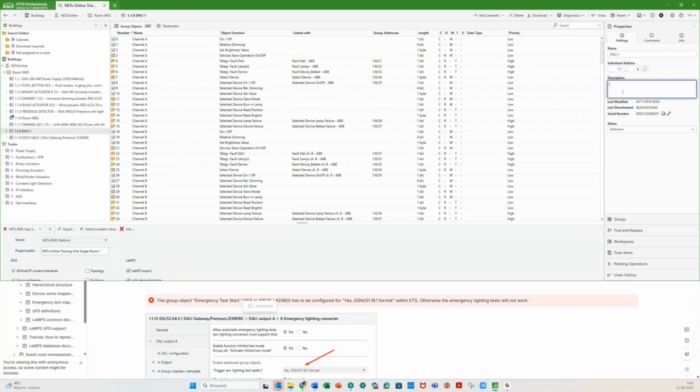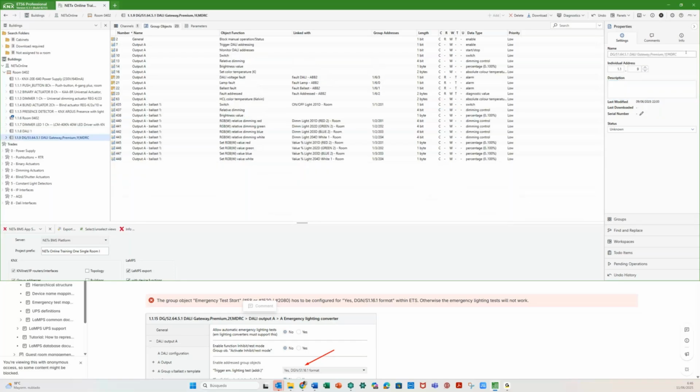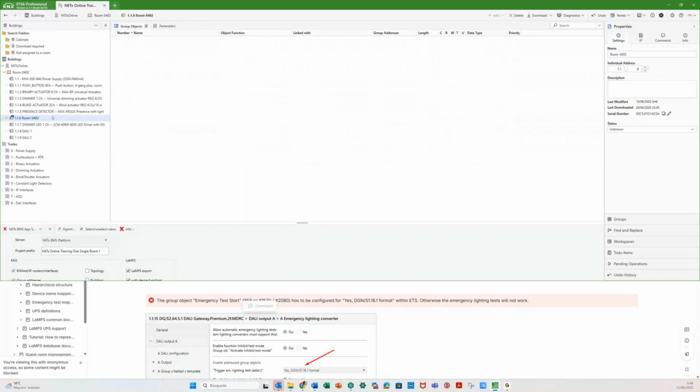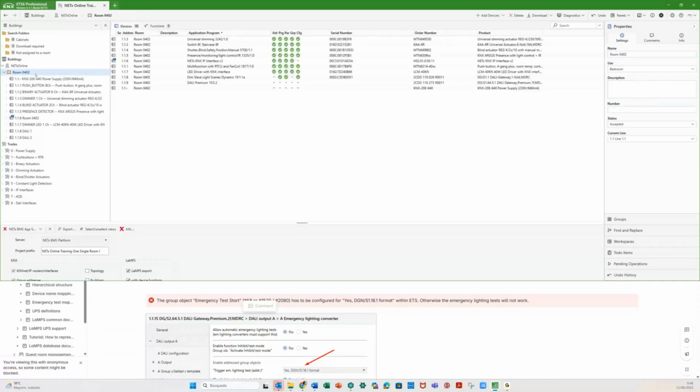And the second thing to comment on was, okay, if you remember, when I exported my projects for different rooms yesterday for KNX, I was just taking into account the room, the name of the IP gateway, the IP address, for example. But you may remember that I also changed the name of the room. It was important, I told you yesterday, because of this lamps module, because it's also considered when you import the ETS structure.